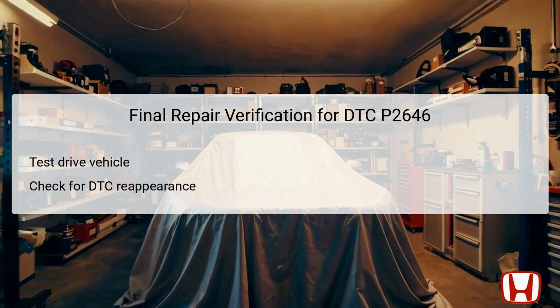Following the test drive, utilizing the HDS again to check for the reappearance of DTC P2646 is critical. If the code does not return, the troubleshooting efforts can be considered successful, ensuring that the VTEC system and rocker arm oil pressure switch components are functioning as intended.